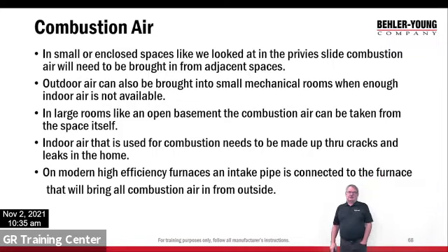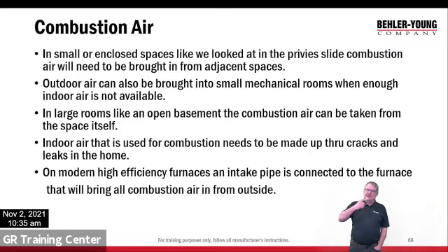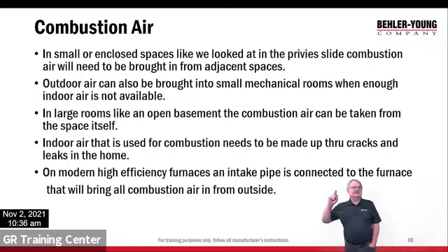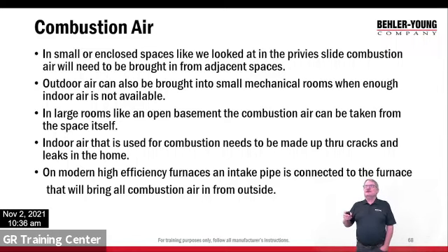So in a large room like an open basement, combustion air may be taken from the basement. In smaller rooms, we might need to add. Now, all this combustion air is coming from someplace. So it's going to come in around cracks. It's going to come in through window leaks. It's going to come in through doors. Modern furnaces now, we bring combustion air in specifically for the furnace to eliminate this problem. But a lot of this equipment's still there.